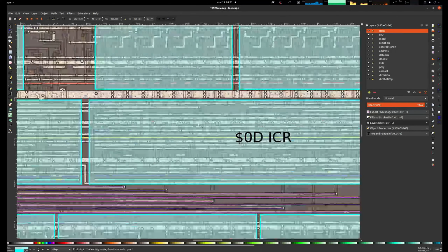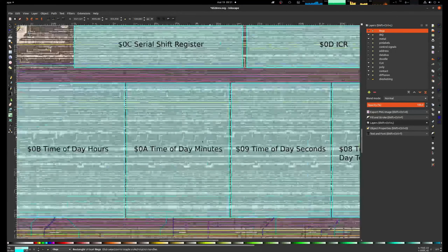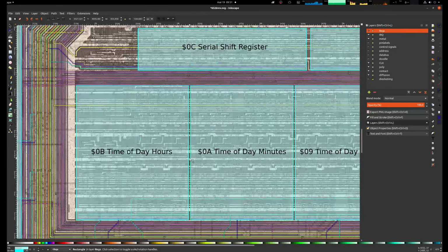And down here it's different. And why is it different? Well, it's a binary coded decimal system. So one digit is going from 0 to 9, not 0 to F. So that means they have decoded every digit. So let's just look at hours here. And you can see in the 24-hour clock anyway, the first digit goes from 0 to 1 to 2. So therefore you have 3 bits.